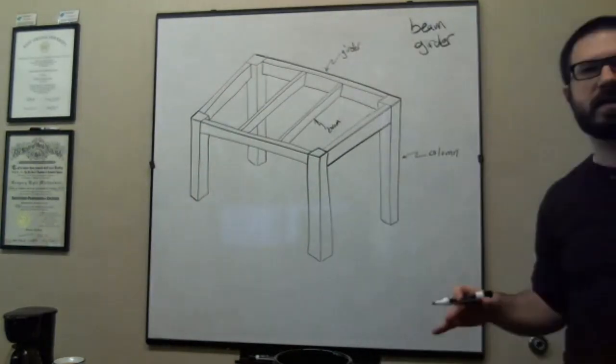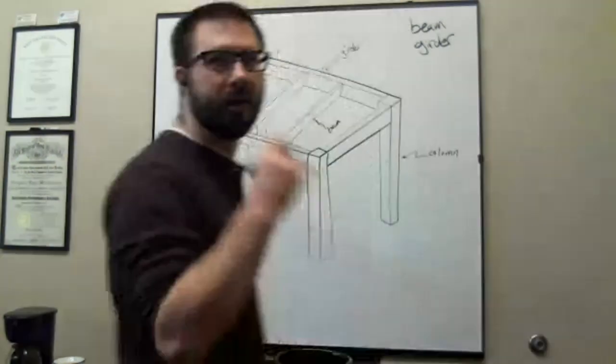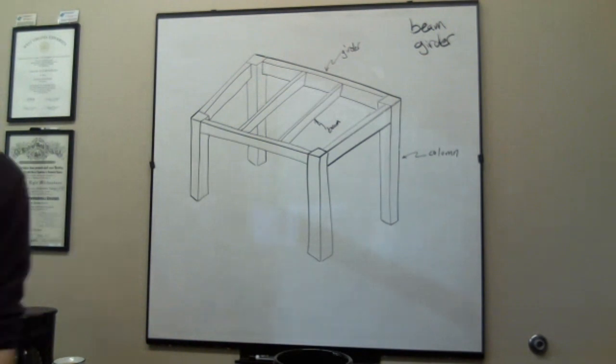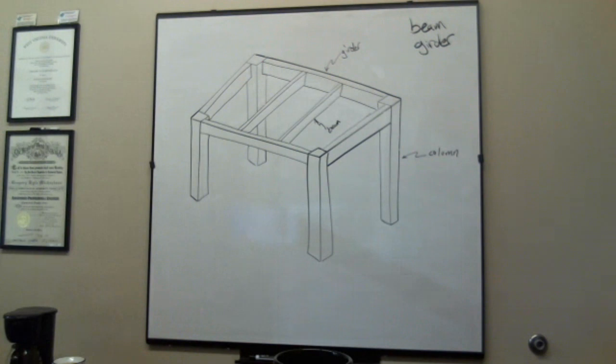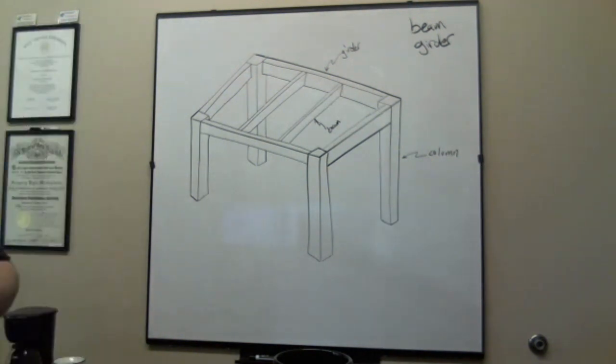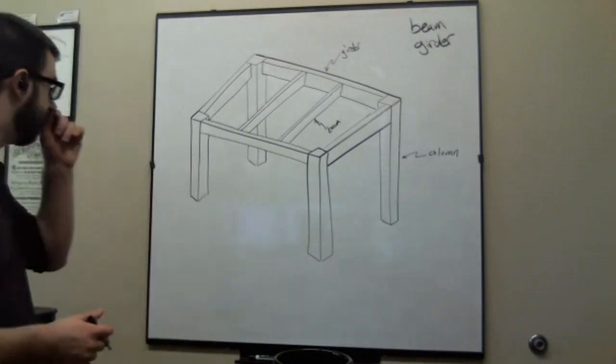Okay, so does that make sense, that idea that the beams frame into the girders? That's the framework I'm going to use. The other point is that this is obviously pretty difficult to draw, at least it is for somebody like me. Do girders typically carry more load? Yes, they do, and that will become very clear here in a second, but you're absolutely right. The reason why is because of the tributary area and sort of the hip bone connected to the leg bone approach with how this works.